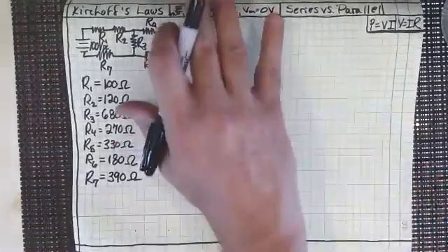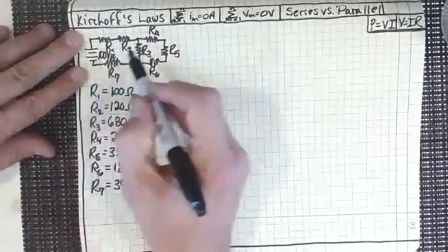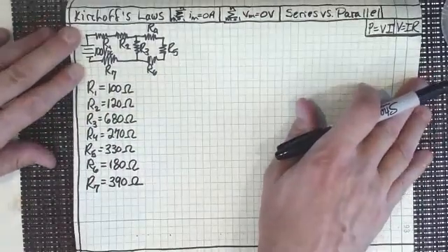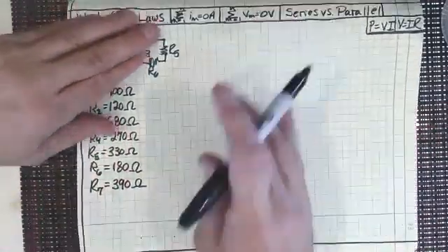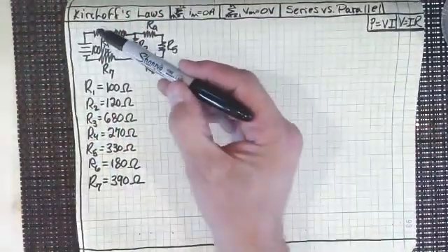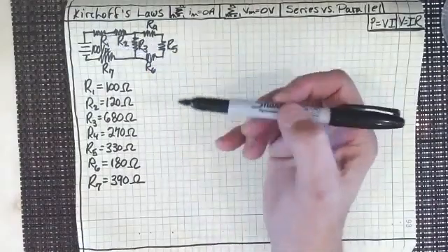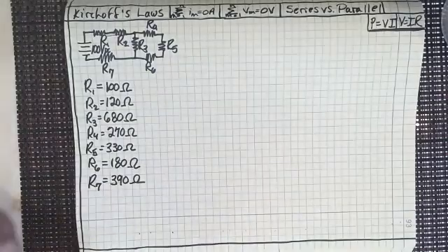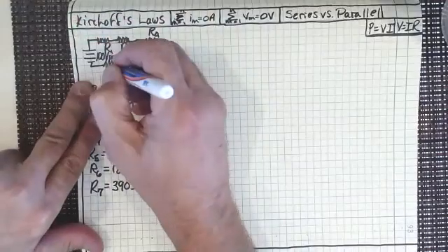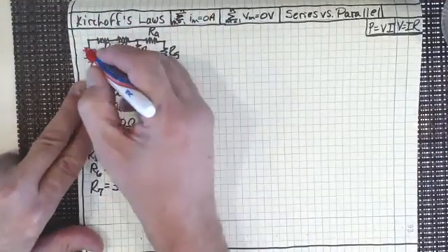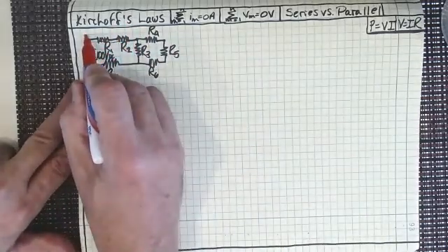All right. So that's our little circuit that we're going to try to work our way through using Kirchhoff's laws and using the fact of series and parallel resistances. So to prepare us for this, because you can see that I've really got things in series here, right? What we really want to find out is what is the current that's coming out of this power supply. It's 100 volts DC, but what's the current that's coming out of that power supply and then flowing through the